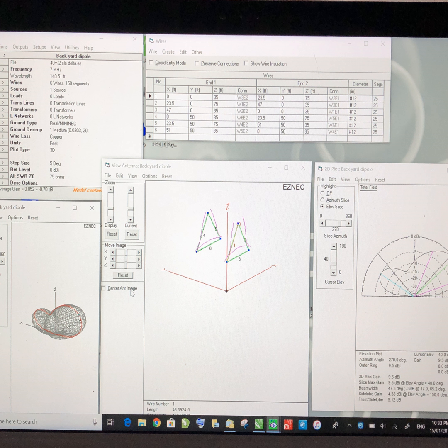So this will give you an idea of the SWR for a given frequency, and it's quite useful for fine-tuning the antenna, particularly before you even plug it into the radio. So what normally happens is when you put this antenna up, for various reasons, sometimes due to ground conductivity, proximity of other objects, the type of wire you've used, you might well find the antenna needs to be